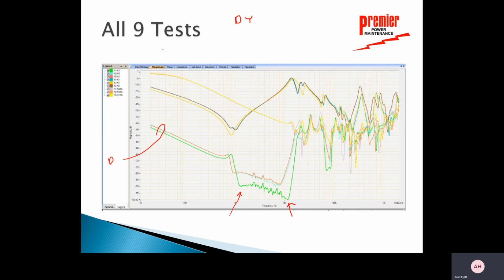And if you'll notice, up on the top left, it tells me the colors. So the colors were green and turquoise and a red there. So if I see the green, I don't see the turquoise and the red. Well, the turquoise and the red have mixed together because those lines are exactly on top of each other, and so it kind of looks like brown. So I've got 2 windings that are exactly on top of each other. I can see a little bit of separation right there, but 2 windings are basically on top of each other, but I see a 3rd winding that's different.